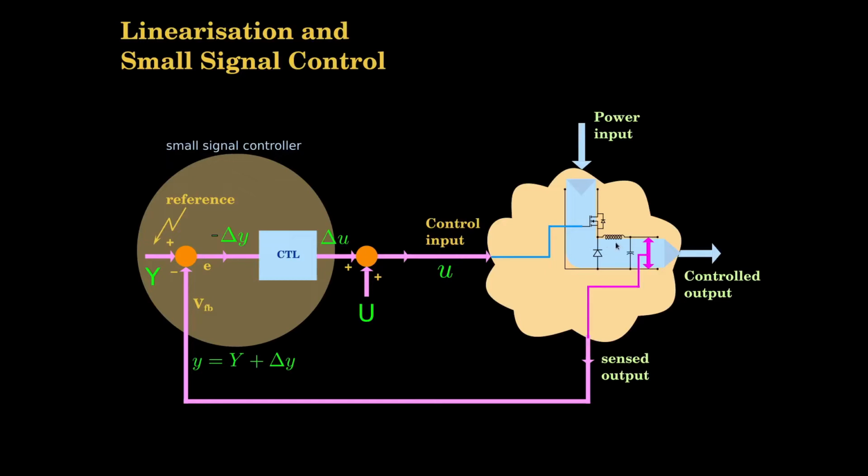Likewise, if we feed back all the state variable information, let us say we have the inductor current. Inductor current is also a state variable, so let's say we feed back that. The capacitor voltage is a state variable, and we feed back that, which we are anyway doing, since the output voltage is directly the capacitor voltage. So that is one variable we have, and then the current information through the inductor.